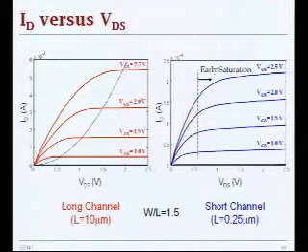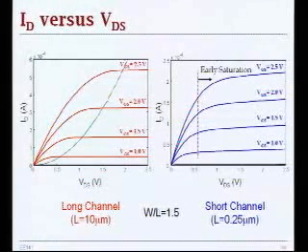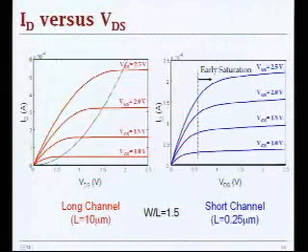All of these second order effects are modeled in your SPICE model files, but if you try to include them all, the equations will blow up in your face and you're stuck. You could be spending the rest of the semester just solving a simple CMOS inverter, and we're not going to do that. So for that reason, we need to do some simplifications here.